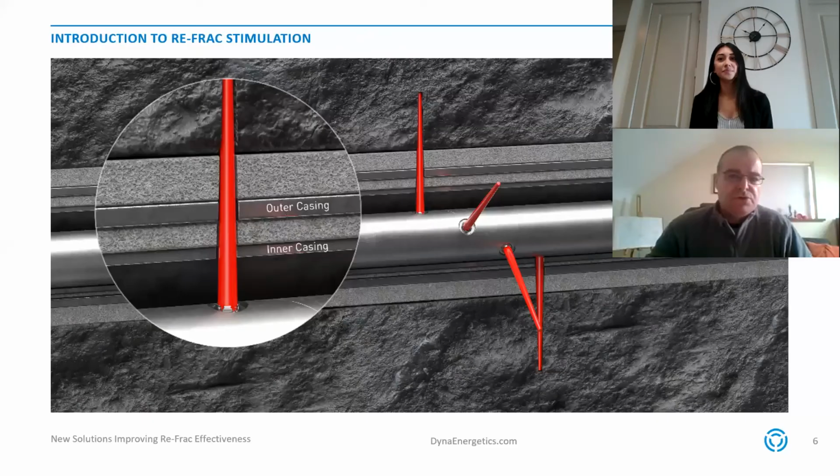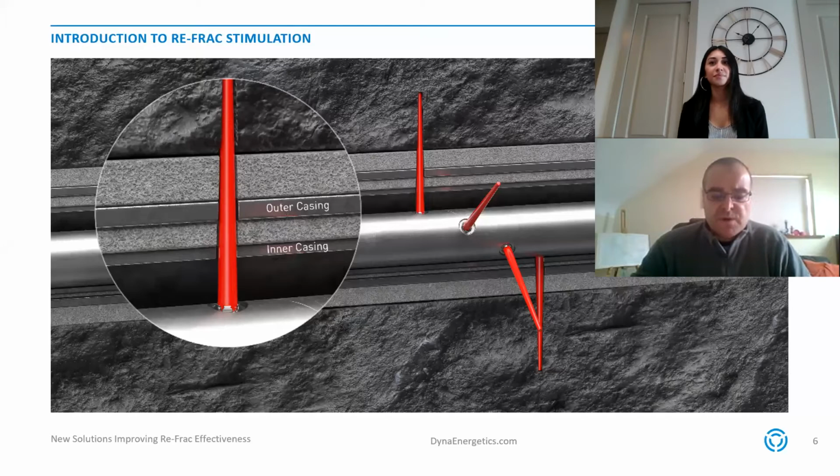Absolutely, Misha. So mechanically isolated wells prepared for refrac operations usually present themselves with a reduced wellbore diameter due to the slimmer casing or tubing that's been installed into the existing infrastructure. Smaller IDs usually also mean smaller guns. Smaller guns mean smaller shape charges. Smaller charges mean less explosives and less energy available.